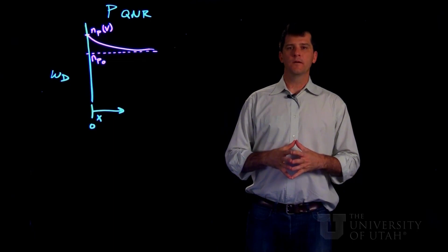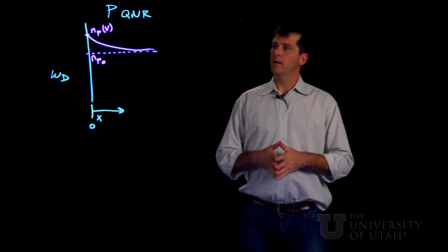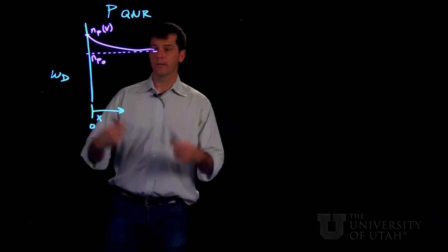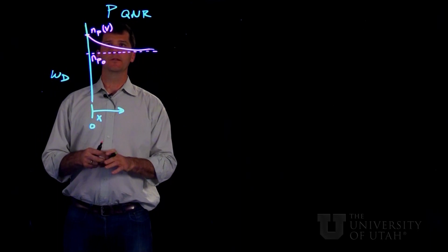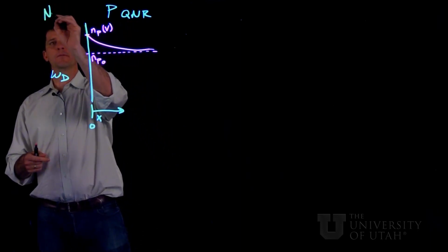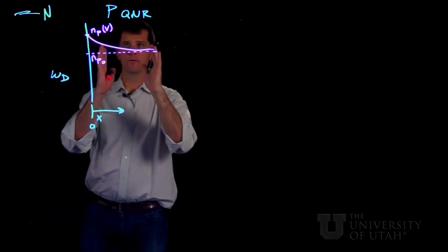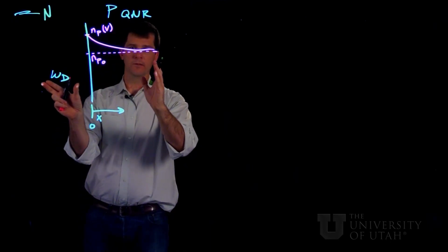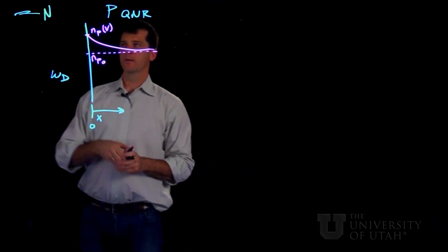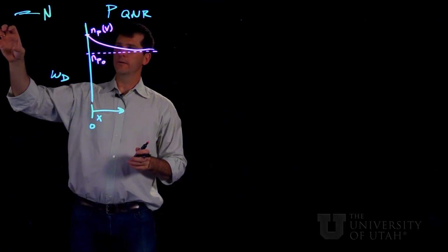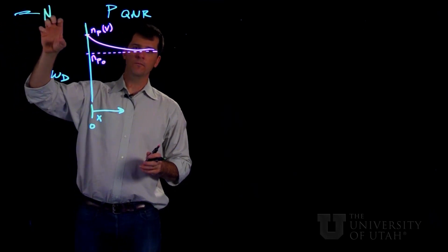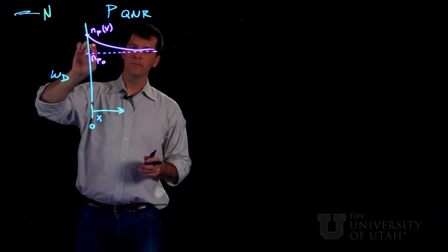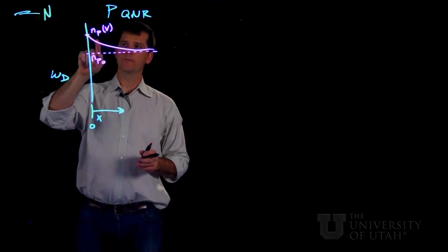Okay, now we've derived our boundary condition, which is voltage dependent. And I've taken the liberty of turning our original PN junction around. So now this is the N-type side over here. And we're just going to focus on the edge of the quasi-neutral region adjacent to the depletion width on the p-type side. So from our last discussion, we were injecting minority electrons from the N-type side of the junction into the p-type quasi-neutral region right at the edge of the depletion width.